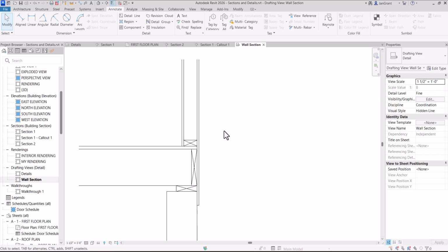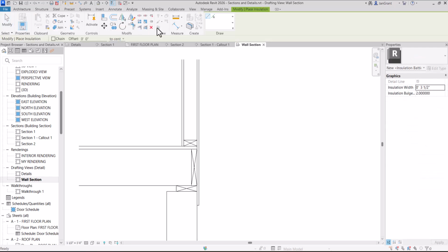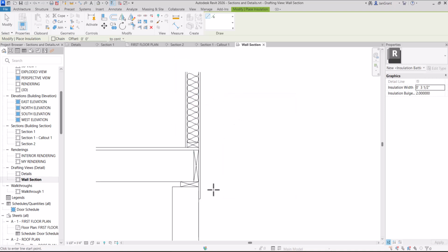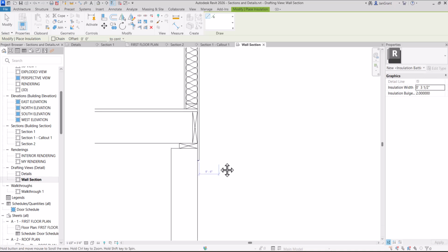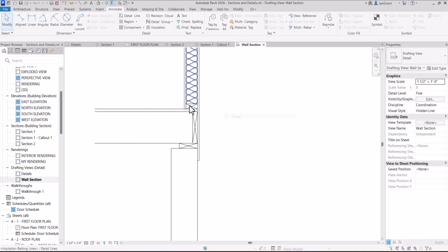All right, and then the insulation is already here for us in this panel. I'm just going to click right on here, insulation. And it says it's 3.5 inches. I mean, we could change that if we needed, 5.5 inches for the 2x6s. But here I'm just going to click the midpoint of this joist and pull my mouse up. And look at that. Nice, right? So there's the insulation, sub 4, all my 2x4, 2x6, 2x10s. And so let's take a look at bringing that anchor bolt in.